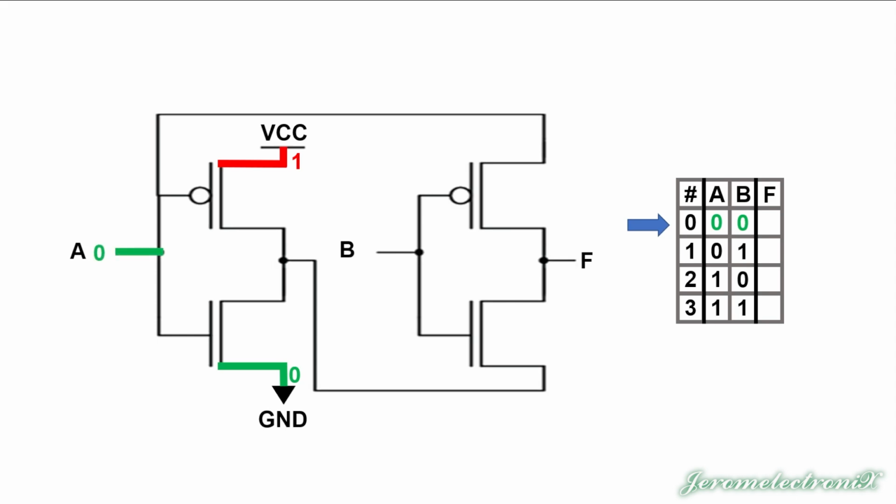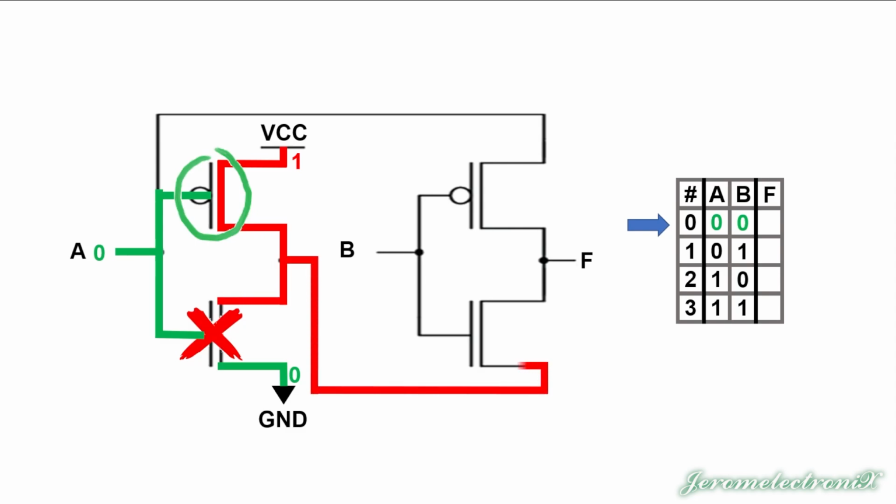A has a 0. That means that 0 is going to flow to the PMOS and the NMOS. On the NMOS, that's going to block the flow through that gate. On the PMOS, that will allow flow through that gate, so we can actually flood the internal conductors as far as they can go until they meet a gate. But also notice that the A input reaches around over the top and down and stops, trying to flow through the final PMOS on that side, but we don't know if it's going to flow or not, because what is B? Let's check the table.